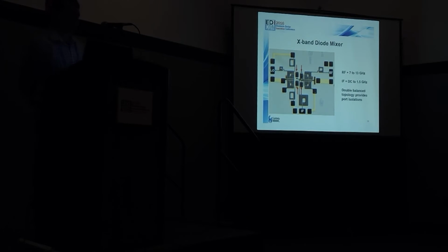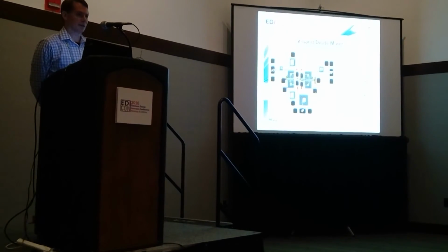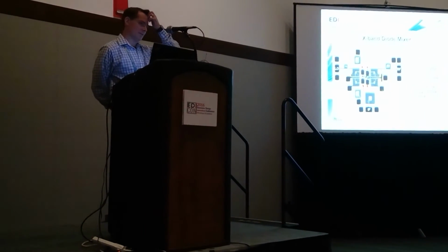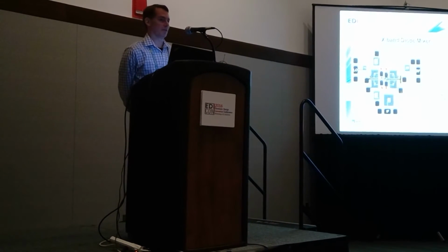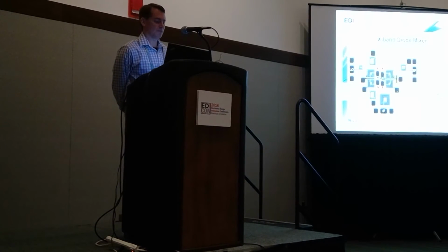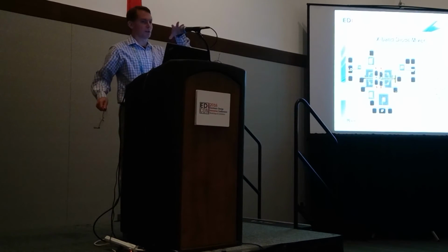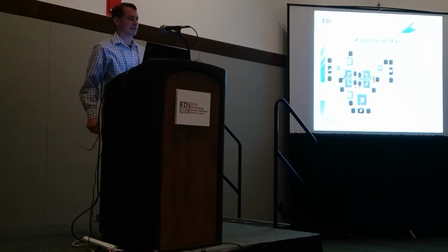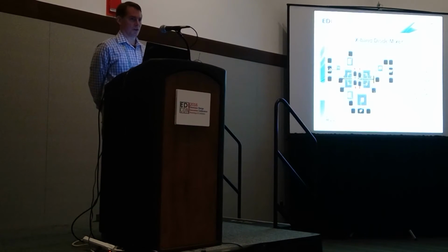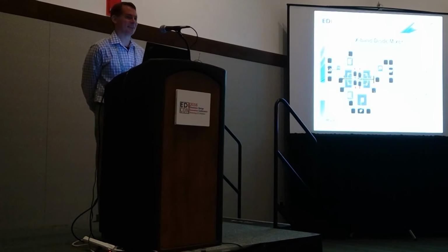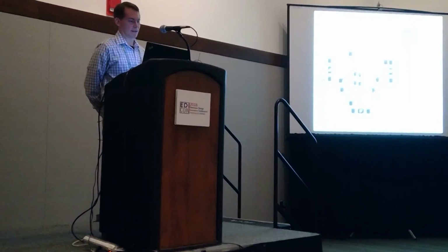Great question. So the first, on the physical makeup of the diode, we're at the mercy of the foundry. We're a fabless semiconductor house, so we contract out our manufacturing to the foundry, and they give us the rules about how they make their devices. Some foundries make diodes with a vertical structure with a rectangular contact area. In this case, this is what the foundry says we can do. We're not allowed to do anything else. They certainly won't guarantee it. This particular foundry makes FETs with gate stripes, and so that's how we make the diode.